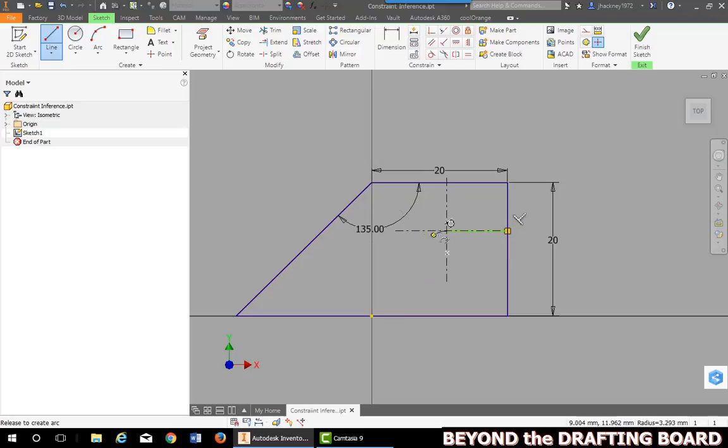If you make a mistake, go back over the gray dot and go in another quadrant. You stop at any angle you desire. You will get alignment points for certain angles, such as 180 or 90. I'm going to go 180, let go of my mouse, and now I'm drawing straight with a tangent constraint added on both ends.